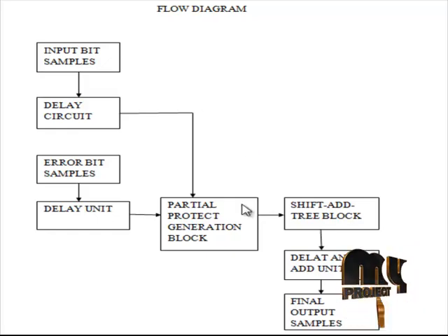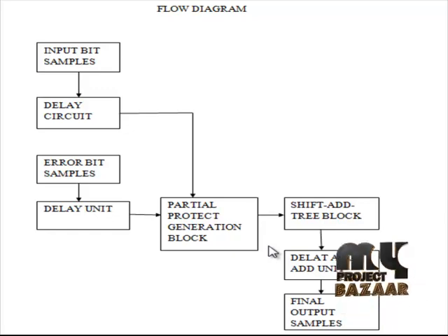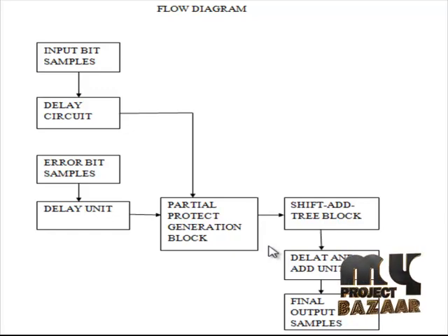Each partial product generation produces L by 2 partial products corresponding to the product of the recently shifted error value. The error value is multiplied with the number of 2-bit digits of the input word signals, where the subexpression is shared within the multiplier. Since the scaled error is multiplied by the n delayed input values in the weight update block, the subexpression is to be shared across all the multipliers as well. This leads to substantial reduction of the adder complexity. The final output of the MAC unit decides the updated weight, to be used as inputs to the error computation block as well as the weight update block for the next iteration.